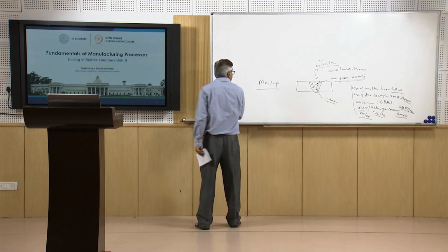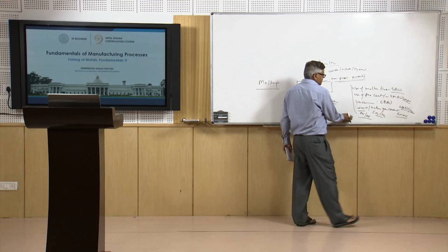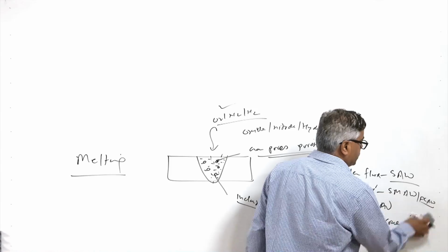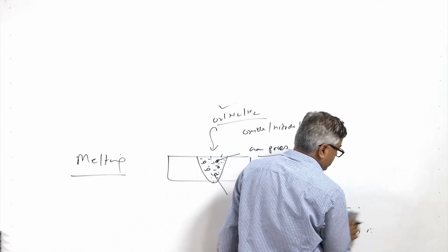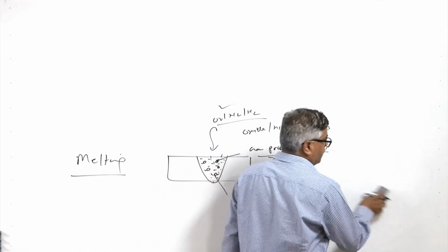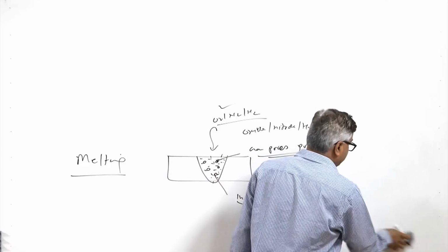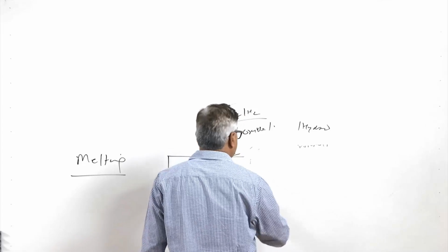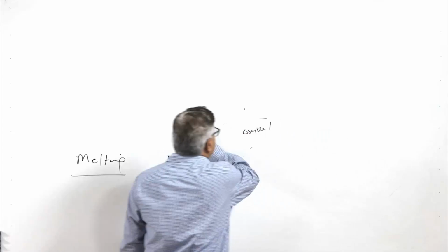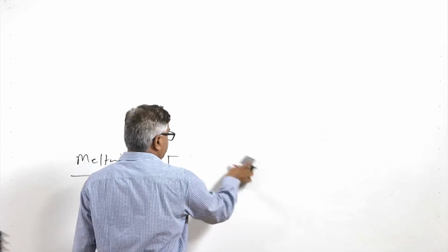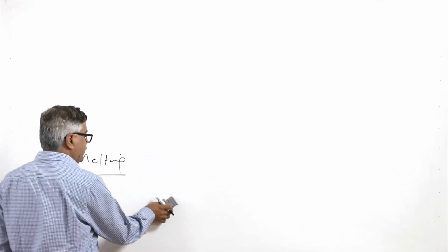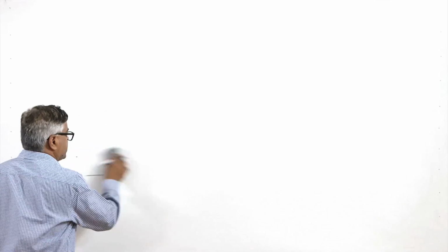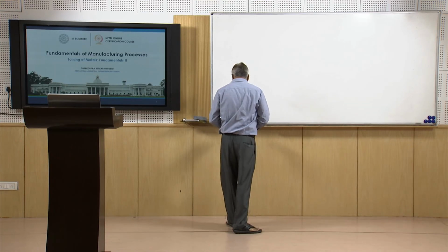Also the availability of helium becomes an issue, because it is not that easily available, and the cost difference is huge, like maybe 4 to 5 times the cost of argon. So, for most of the commercial purposes, like the welding of pressure vessels, where reasonably good quality welds are required, argon is used as a shielding gas, while helium is preferred for very high quality weld joints, because it is very costly and very high flow rates are needed when helium is used.